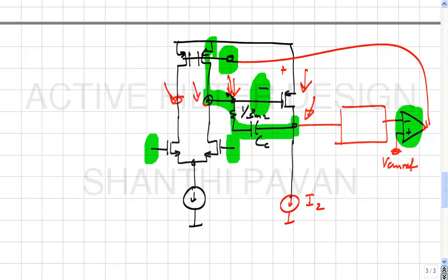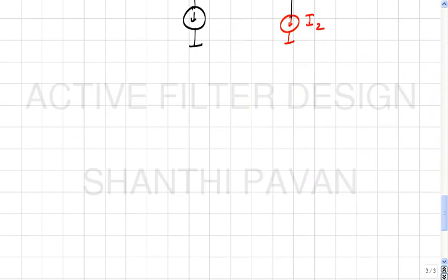So if this output common mode does not come up, the input common mode of the next one has also not come up, which means that the output common mode of that is 0, which now feeds back to the input common mode of this. You understand what is happening. We said that just like in a GMC filter, an active RC integrator, a fully differential active RC structure, while there is negative feedback for differential signals, for common mode signals there is positive feedback.